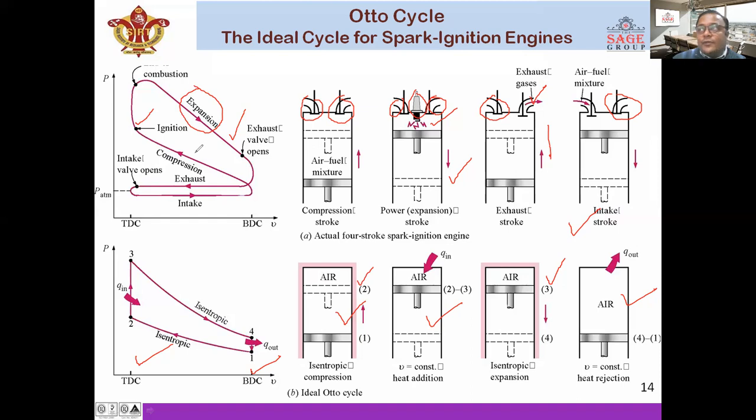So in the ideal cycle, it is not necessary that all these processes are constant volume, constant pressure or isentropic. It does not follow the thermodynamic rule or the ideal gas process. These go differently, in the different manner in which it actually happens in the engine cylinder. The actual process takes place in the engine cylinder, and the suction takes place at the lowest pressure condition. Exhaust takes place at the uppermost condition, or the highest pressure. It is depicted in the PV diagram.